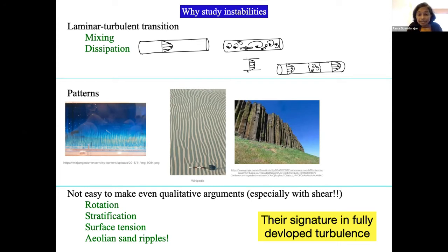The turbulent velocity profile on the mean looks like this. It looks very clean and smooth. And the beauty is that given the Reynolds number, given the pipe roughness and so on, this velocity profile is invariant. So you can come back tomorrow and do the experiment, day after tomorrow, go to another pipe. Everything, all the mean properties are invariant in turbulence, which is why we need to study turbulence. If it's going to be a completely random phenomenon, then we can't predict anything or we can't go anywhere with it. But that's not how it is. We can predict so many things about turbulence, which is why we study it.